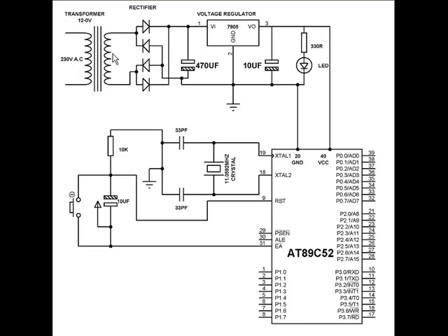have a step down transformer and then we get 12 volt AC. That 12 volt AC passes through a bridge rectifier. That bridge rectifier gives me filtered pulsating DC. That pulsating DC is further filtered, so I get a 12 volt DC here, and the 12 volt DC passes through a voltage regulator and we get 5 volt DC here, because the voltage regulator is 7805, and this LED is connected to indicate that the 5 volt DC is available. This is required when it is used with supply voltage from AC.